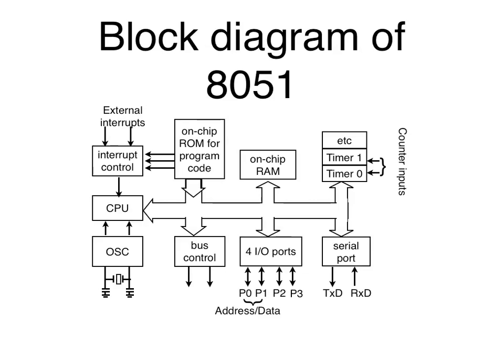Most of the chip actually is devoted to everything else, including interrupt control, oscillator, on-chip ROM, bus control, on-chip RAM, GPIO, timer, serial port, and all that. And the fat arrows are really this internal bus that connect all these things together.